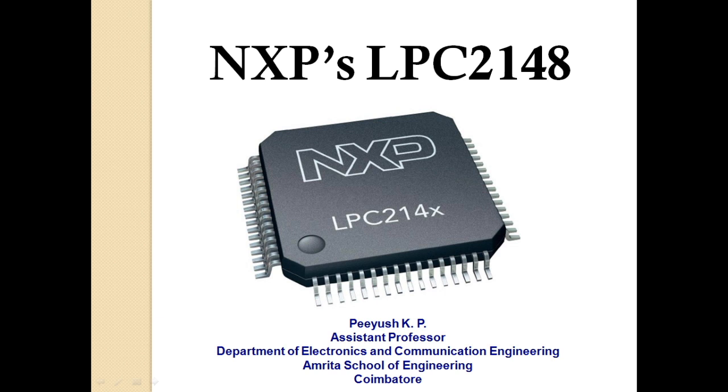It has the ARM7TDMI-S as the ARM core, with all the additional peripherals, and is given the name LPC2148. LPC shows that it is a microcontroller from NXP, previously known as Philips.